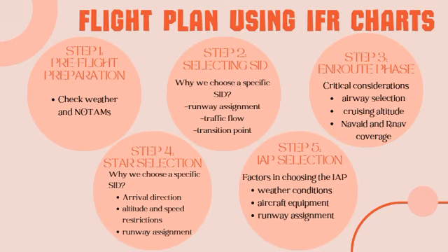Now I will guide you through an example of planning a flight using IFR charts, in which we will explore each phase of the flight, departure and route, arrival and approach, highlighting the critical decisions and the reasons behind them. Step 1 is the pre-flight preparation, in which we will check weather and NOTAMs to be aware of any airspace restriction, navaid interruption, or airport-specific issues that could affect the flight.